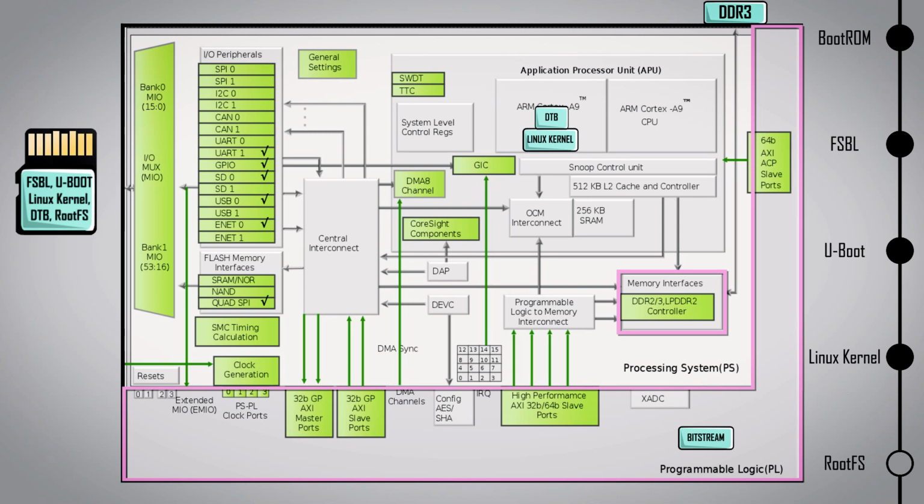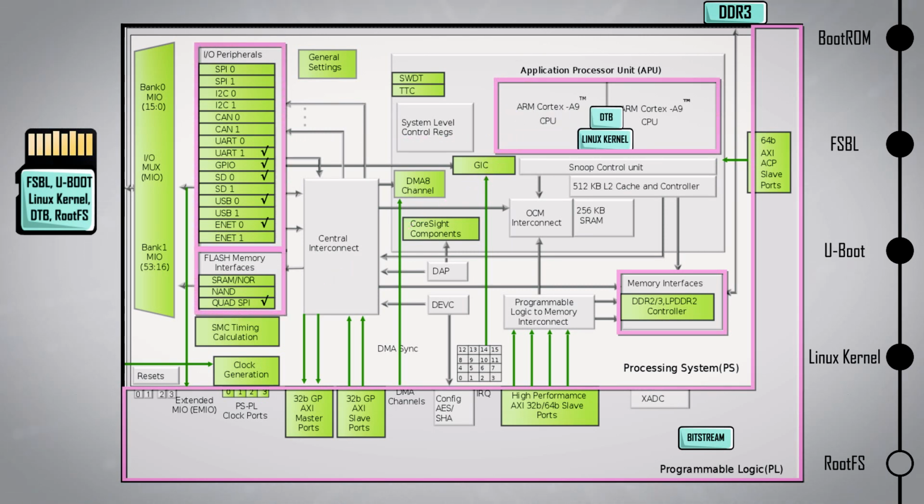The hardware that both U-boot and the Linux kernel are configuring may be hardware that hasn't been configured yet, or hardware that has been configured but needs to be reconfigured so the software execution can operate more optimally. Finally, the kernel will grab some parts of the root file system from the SD card and place it into DDR3. Luckily though, the kernel doesn't need to grab the whole entire root file system since it's pretty big. It just needs enough to mount the file system so there's a known and established pathway from the CPUs, and also run the first process called init that proceeds to spawn a few more processes to provide a good user space for a user to interface with.